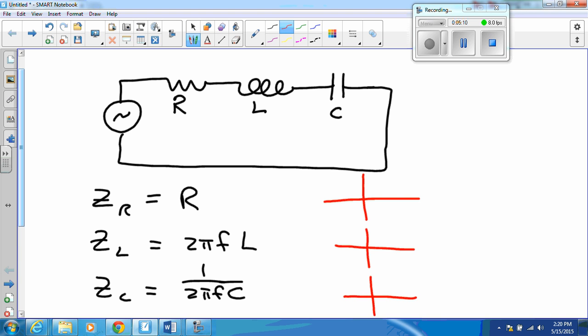And that is this: when you have a resistor, we can think of that resistor's impedance as being a vector whose magnitude is R and whose direction is 0 degrees in the plane. Now, the 0 degrees is going to correspond to something real in just a minute, but right now we're just thinking of this as a mathematical model. It's imaginary.